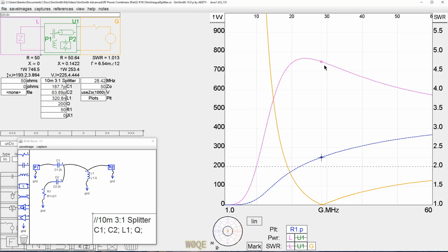That looks really good. So now the dipole has 747 watts applied to it. The Yagi has 249. That's pretty much exactly our 3/4 of the power and 1/4 of the power. The SWR at resonance, as seen by the generator here, is 1.013. I'd call that good enough.